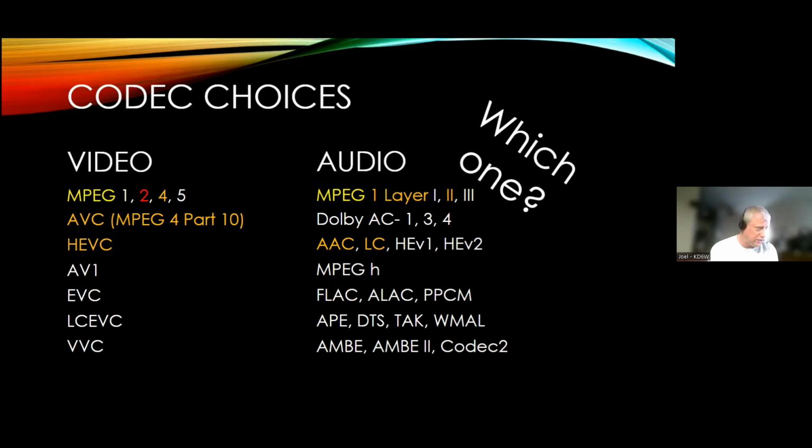HEVC just came out recently, over the past couple of years, so it's pretty fresh ink. But HEVC and AVC are steps above MPEG-2 in compression efficiency. When people compare AVC to MPEG-2, they'll say AVC is 50% better or stronger compression, with better tools than MPEG-2. So at the same bit rate, the AVC picture will look better. And when you compare HEVC to AVC, HEVC is 50% better than AVC at the same bit rate, so the picture quality will be better.